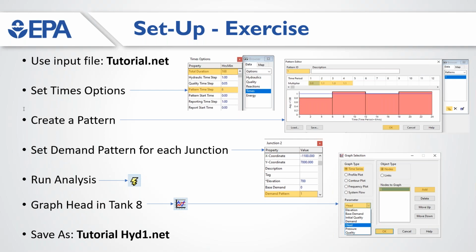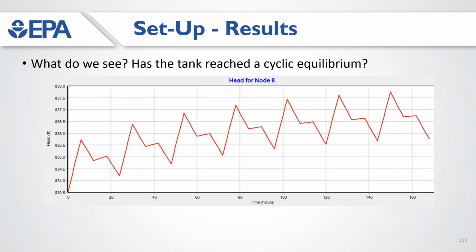Okay, hopefully everyone was able to follow these steps, and these are the results. This is what your time series graph of the head for node 8 should look like. The double peak that repeats daily is caused by the pattern. Do you think this looks like the tank has reached an equilibrium? Or does the head stop increasing with each pattern iteration? We can see it hasn't, because if we compare the same point in the pattern's shape for each iteration, it is higher than the previous day.